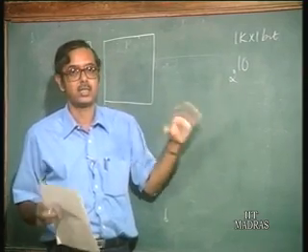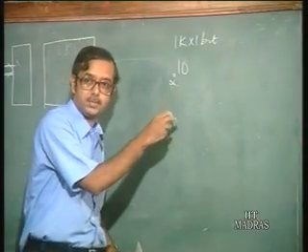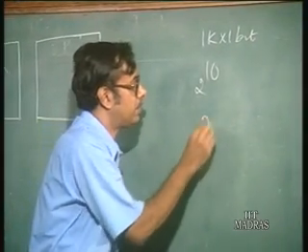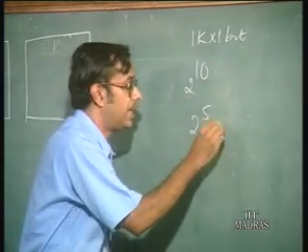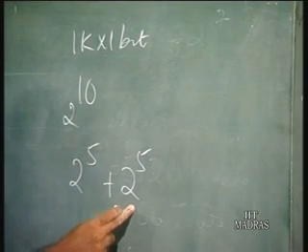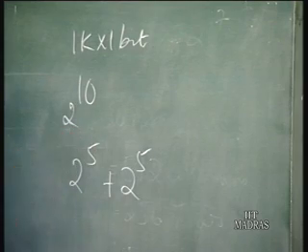So what you do is a 2-dimensional decoding, that is, you have two decoders each of 5 bits. So you have one 2 to the power 5 decoder, and another 2 to the power 5 decoder. So you have just so many lines now instead of 2 to the power 10 lines. It's just 2 to the power 6 instead of 2 to the power 10. So that is the advantage.